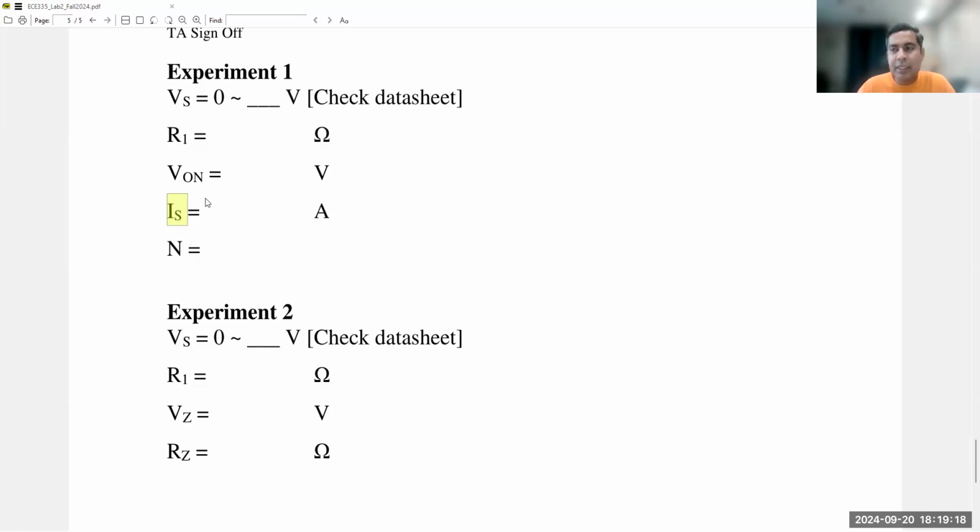It is similar to the PN junction diode, so you may not have to mention it here. But the more important parameters are the Zener voltage, breakdown voltage, and Zener resistance. For those, you have to do the hand calculation, the simulation, and the experimental deduction for those three, and then compare them in a similar manner in the table.